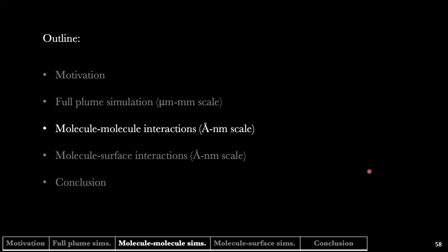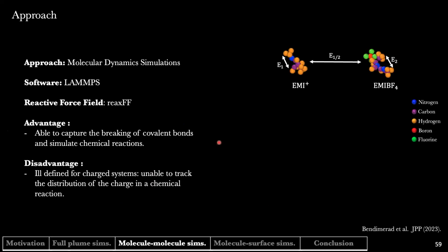So first, let's talk about molecule-molecule interactions at the angstrom to nanometer scale. So the approach here is molecular dynamics simulations. The software that I used is LAMMPS, which is a dedicated software for MD simulations. And there is a critical step in MD simulations, which is the choice of the force field. And here we use a reactive force field, the ReaxFF.